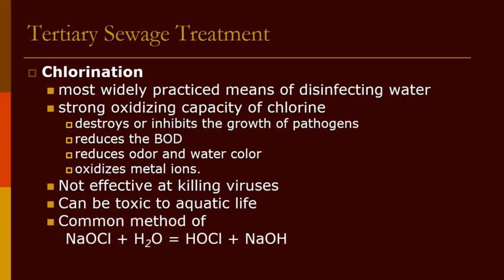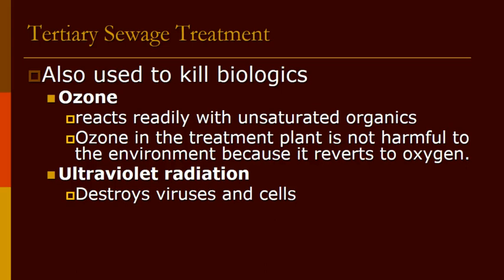The one thing about chlorination, though, is that it does not kill viruses, and if you don't dechlorinate properly, you are going to have toxic water, and that is bad. So chlorination is great, has some pitfalls, but it's also very inexpensive to do because chlorine is really inexpensive. I mean, you're essentially talking about bleaching the water, right? Now, some other things that people do.